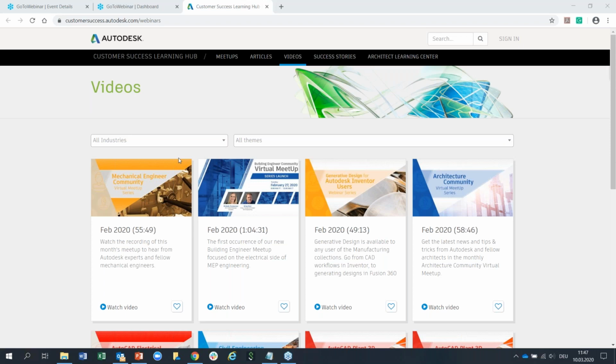So this cannot work, especially if there's no part available in the new spec at all that was available in the spec before of a certain kind. Then what shall the system do? Apart from these logical problems, in my experience, Plant 3D doesn't work well with changing specs. It does try to do things, but it does sometimes damage your descriptions. You get a mess up between properties. That's what I've seen before when changing specs which are really not the same. And so here I would be very careful.